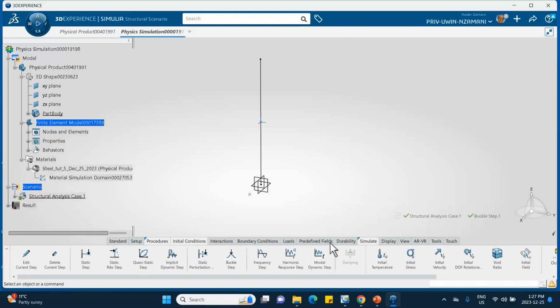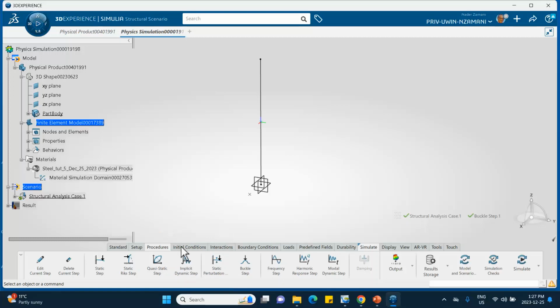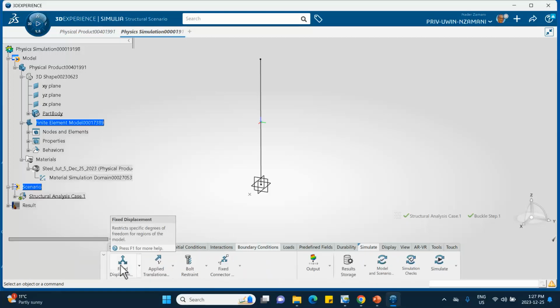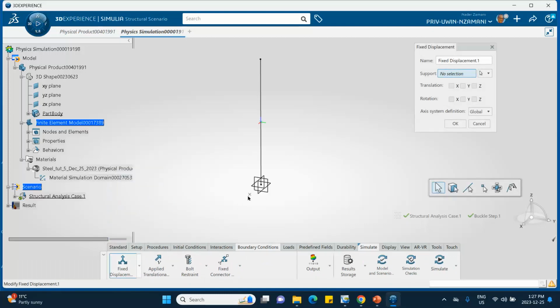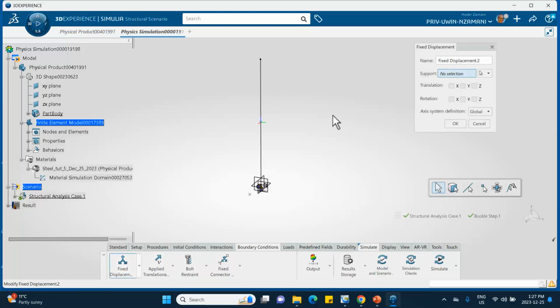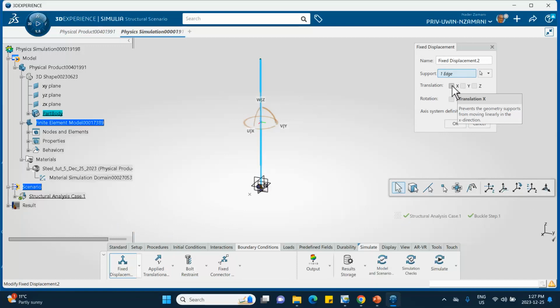So, I'm going to do boundary conditions, and let me unpin these so that we can see these easier. So here, what is that? Boundary condition. We can do a clamp at the bottom, or we're going to do a fixed displacement. All 6 degrees of freedom are fixed. That essentially becomes a clamp. And then this whole line will not go in the direction X. That's restricting it from being a three-dimensional problem. So we go to fixed displacement, that entire line, and no displacement in X, rotation X, rotation Y and Z are 0.